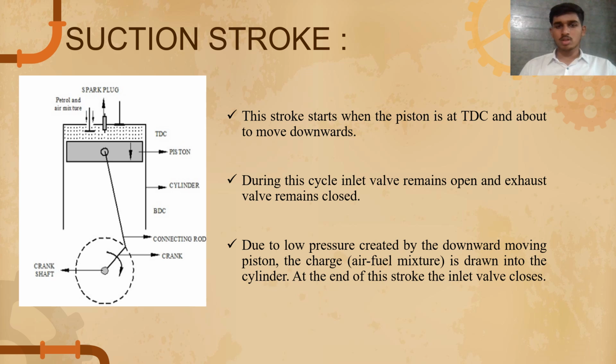So coming first, suction stroke. This stroke starts when the piston is at the top dead center and about to move downwards. And during this cycle, the inlet valve is open and exhaust valve is closed. And due to the low pressure created by the downward movement of piston, the charges, which are the mixture of air and fuel, is drawn into the cylinder. So the work is going to be done on this mixture of air and fuel. At the end of the stroke, the inlet valve is closed.